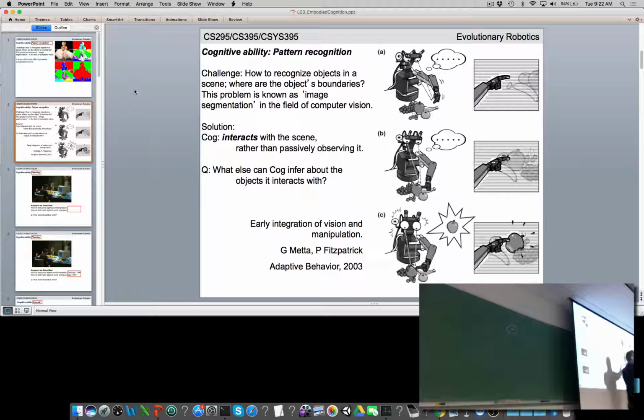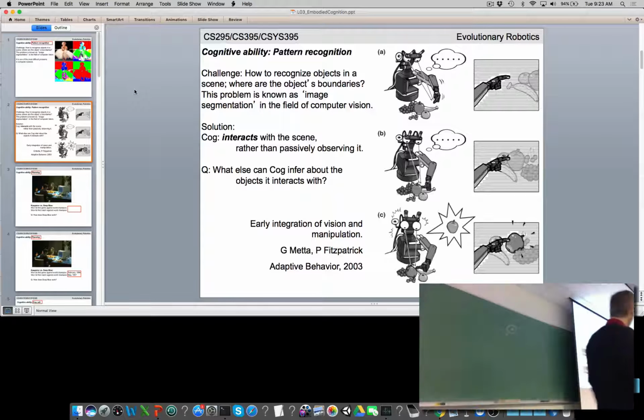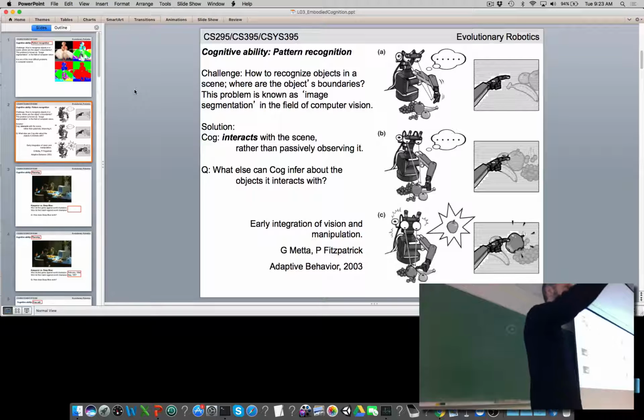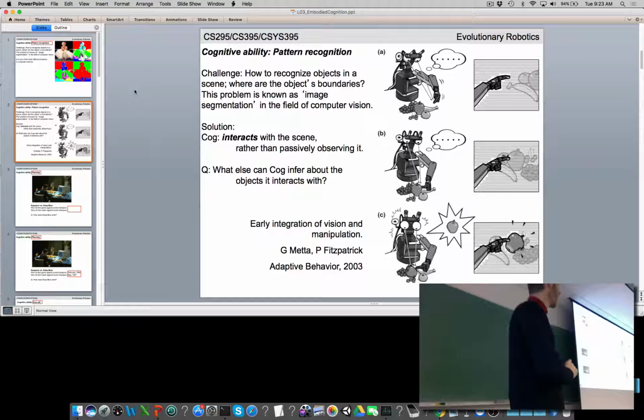So they take those 2 images, put them over one another, and a little computer vision algorithm goes through these combined images and determines whether each pixel registers movement or not. In essence, they're taking not just the current pair of images, but the one from the time step before. If the brightness of the pixel changes from time step t-1 to t, that's motion. If there was no change in brightness at that pixel, no motion. You can see this in the cartoon here. Everything that's grayed out is part of the robot's visual field in which it's detected no motion in the last few milliseconds.